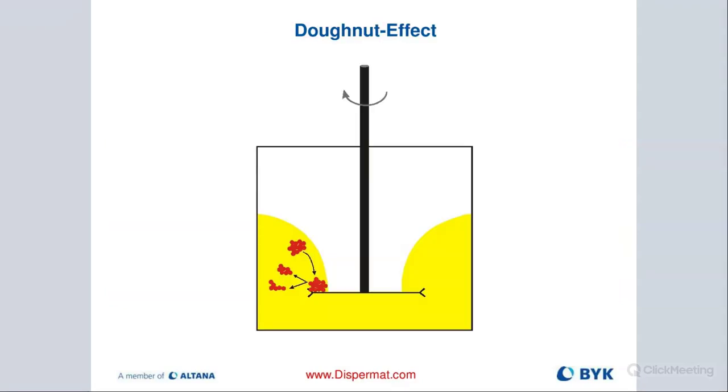That's actually a better picture here where you can see it. The material would hit the tip of the blade, these teeth. The blade is spinning again at about 18 to 25 meters per second to be in the ideal tip speed window. And then the teeth would really break up these binding forces and reduce these larger particle clusters to the smaller aggregate clusters.